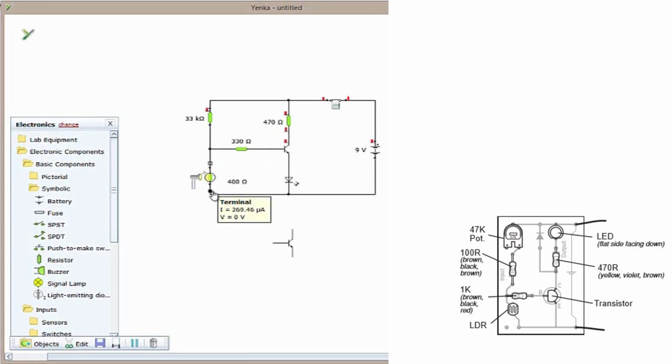In light conditions, low resistance, the current flows in this direction. As the resistance increases, more current is forced to take an alternative route, therefore switching on at the base leg to allow power to go from the collector through to the emitter. Thank you, transistor. Thank you, potential divider.